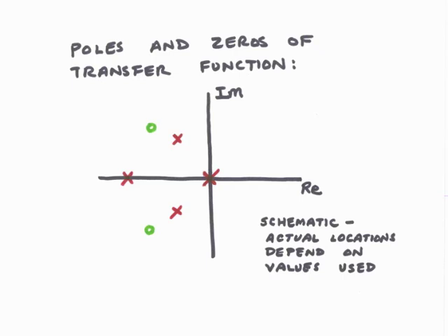The unit step in this summation, due to the pole at the origin, indicates that the impulse response will not decay back to zero. Therefore, we know that the system will not be BIBO stable, since the area under the absolute value of h(tau) curve is not finite. That's not surprising. We know with a pole at the origin that we cannot expect bounded input, bounded output stability. With the pole at the origin, this system will not have asymptotic stability.